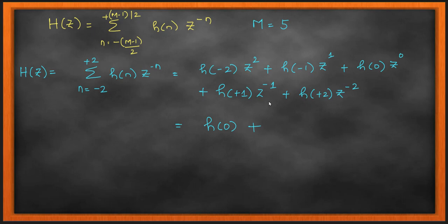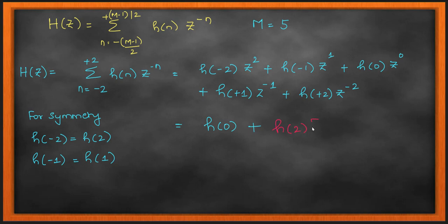What I'm trying to show you is the symmetry across the origin. When I am talking about the Fourier series method, your Fourier series indicates that your samples are extending from minus infinity to plus infinity, which means my FIR filter is also from minus infinity to plus infinity, and that is not possible because that is not going to be finite.